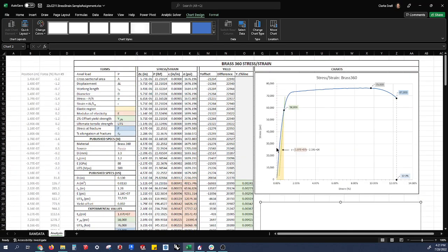Another really helpful tidbit for you. Remember, this is not something you're doing just for an assignment. If you got this data, let's say you had done this experiment and you brought it in, the first thing I would do is quickly plot the data. You could even plot it without doing the conversions. Because, for example, it's just a convention to have stress be positive. It could be negative, and it might be negative in the presets on the Pascal you're using. Who knows? So this might look funky. It might look backwards and upside down. It might just look upside down. So if you plot it quickly, then you can realize you need to adjust your data so that you can get the graphic you want or the display form that you want.